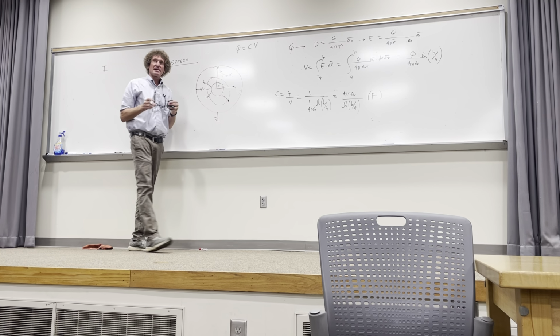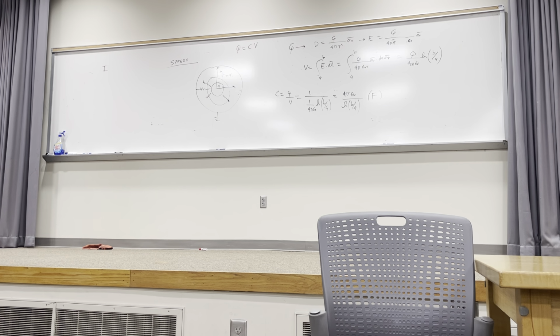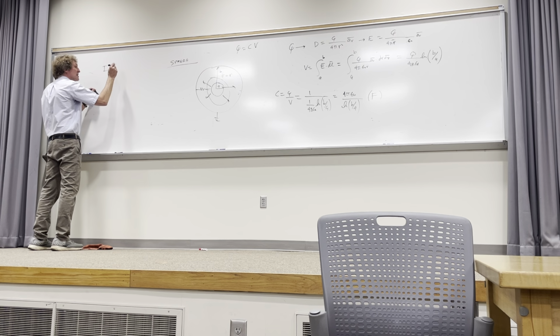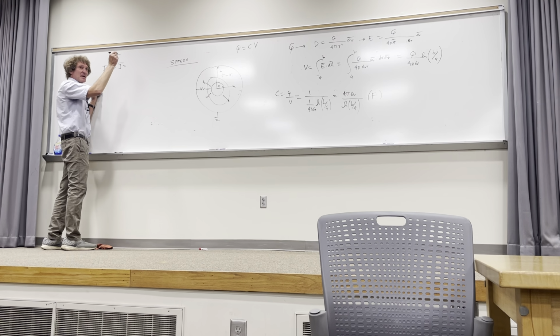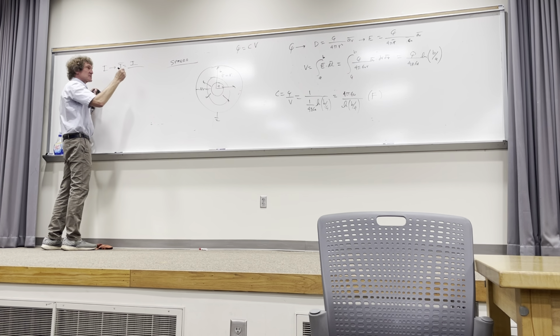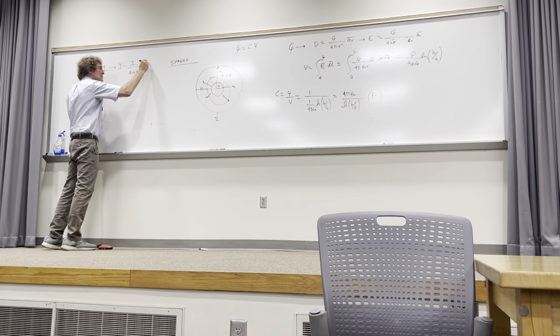How does it get to the inner conductor? Some very small holes drilled and connected, some insulated wires connected to it, and we ignore the effect of that small hole. That's the idea behind it. All right, so I assume I, what next, guys? Get J. Right, very good. And what would J be? You're exactly right. I over the surface area of a sphere, which is 4 pi r squared in the AR direction.